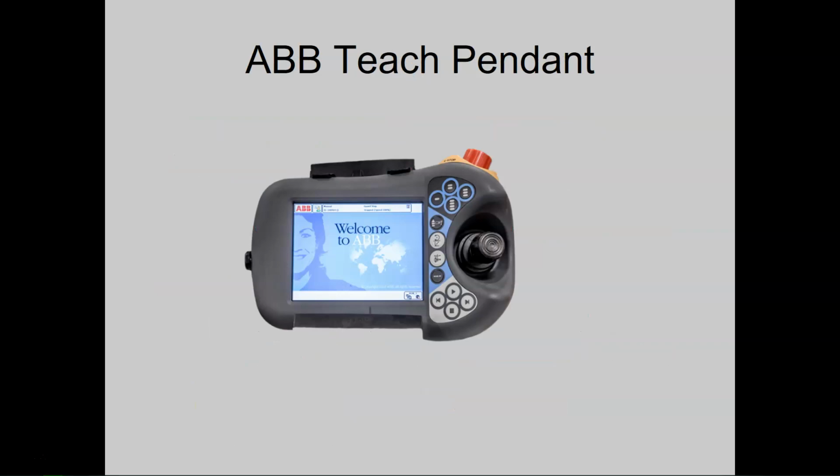So here's a teach pendant from one of our robots. It's the ABB. Cool thing about this is that you have a joystick to move the robot. The not so cool thing is that it can only move 3 of the 6 axes at a time. You have to switch it over before you can move. So you can move the 2 shoulder joints and the elbow joint, but you can't move the wrist until you switch it over and tell it you want to move the wrist only.